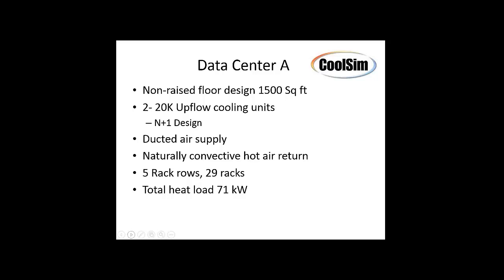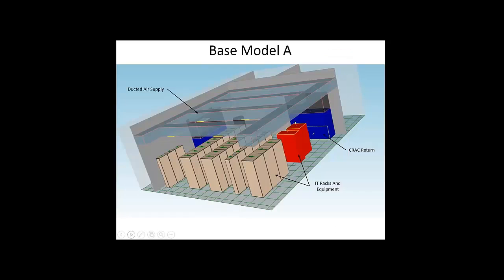I'd like to point out that CFD modeling is not exclusive to only big data centers. It's very helpful in small data centers. In fact, often more helpful in small data centers because you've got less volume and more room and things are swirling around even more vigorously than they might be otherwise. This design is not an air handler in the sense that it's got an outside chiller. So this one is an on-off state. So we're going to shut one of them down and just look at it when it's running under one unit. This is a shot from the CoolSim 4.4 modeler.